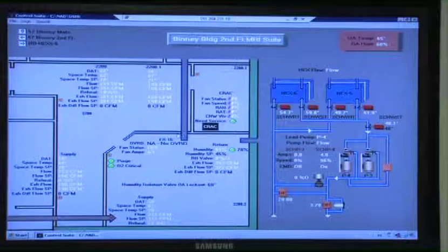Let me ask you this, Jimmy. From this graphic, I don't know how accurate this is, not wicked accurate. Is this the exhaust over here and the returns over here? Supplies over here in the room? Do you remember, Steve, at all? No, that is not the case. The return comes out around where that angled wall is. The return leaves the room there. There's a VAV box just outside that door. In order to get them in the room, so that the information fit, it needed to be reversed.